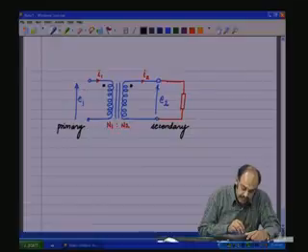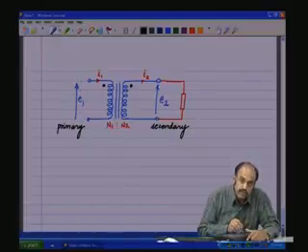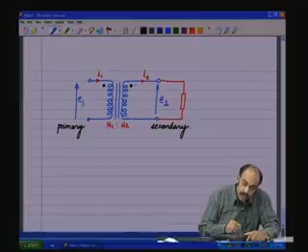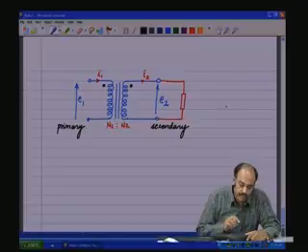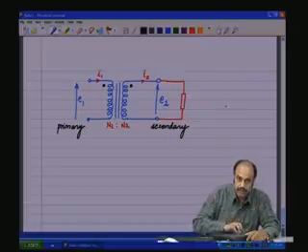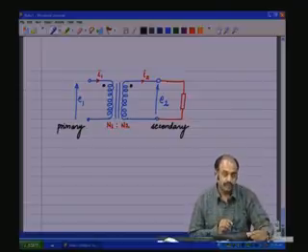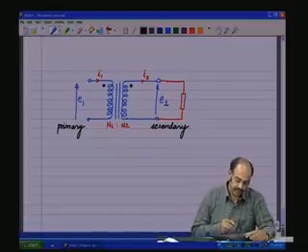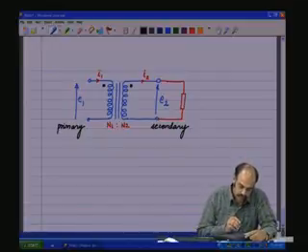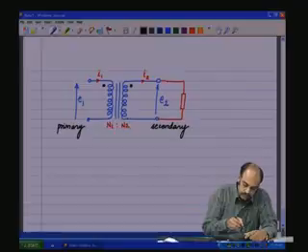When the current is entering the dot and this is positive, energy is put into the transformer. The dot side is positive, current is leaving the dot, energy is removed from the transformer. So, that is how the energy passes through the transformer and goes from the primary to the secondary side.